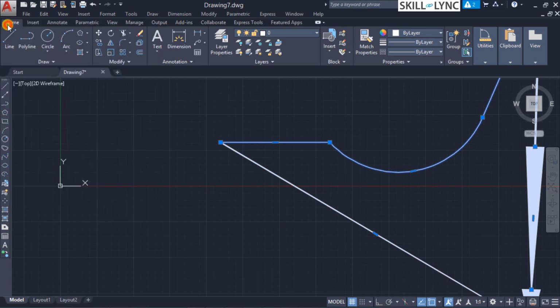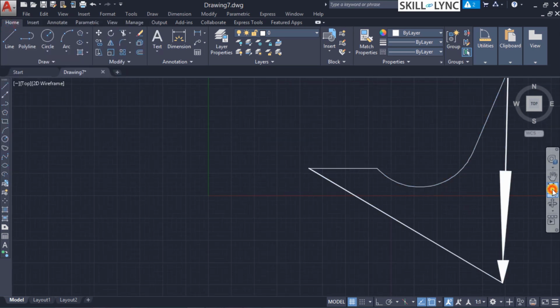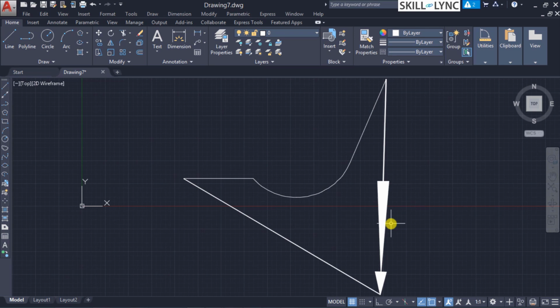But this PEDIT command is a comprehensive package containing all the commands. So it is used to move the polyline, edit or delete the individual vertices, that is, individual vertex points we can have control over. Next, we can apply a uniform width throughout the polyline segment, or as specified here, we can control individually each and every polyline segment.